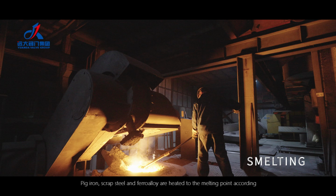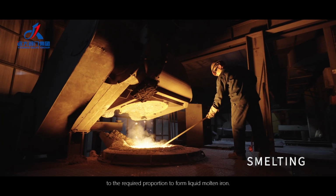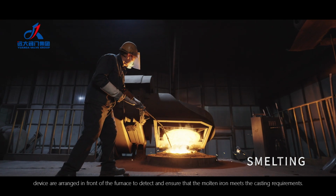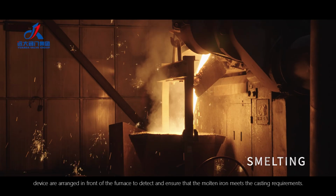Pig iron, scrap steel, and ferroalloy are heated to the melting point according to the required proportion to form liquid molten iron. A chemical composition rapid analyzer and a rapid temperature measuring device are arranged in front of the furnace to detect and ensure that the molten iron meets the casting requirements.